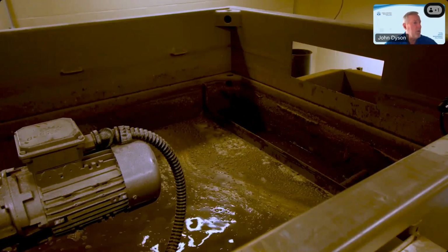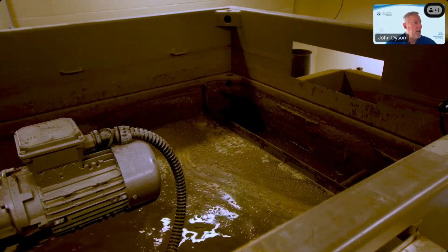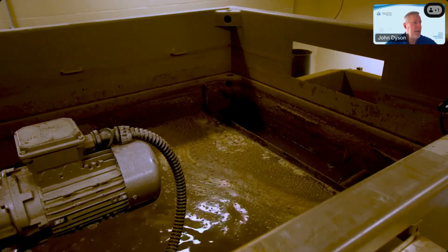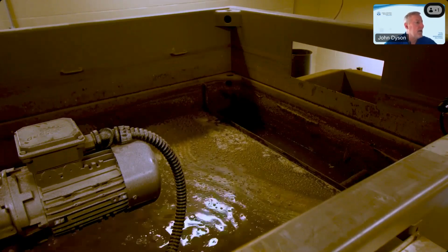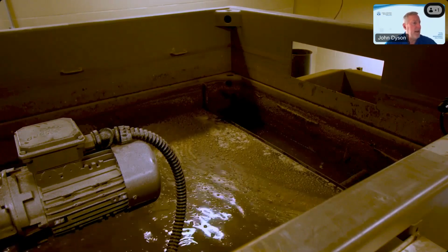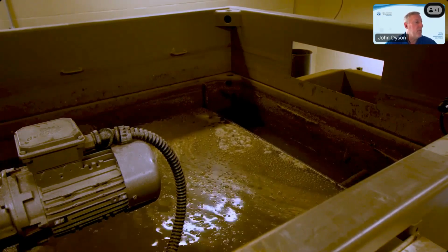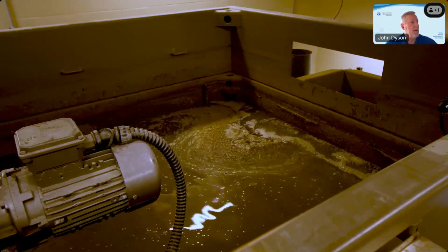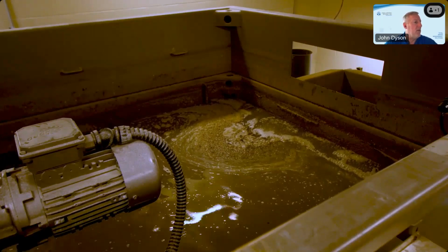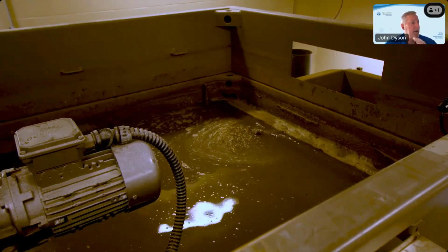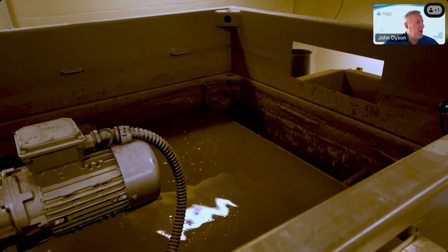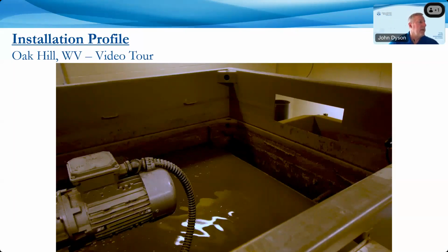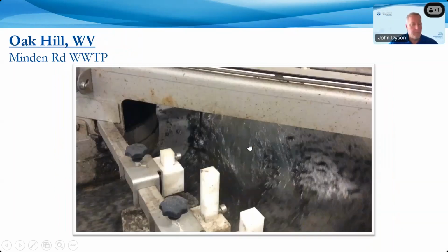Now scum removal, and I like to show this, is it's coming up like for a normal backwash, and this scum removal is generally done every 8 to 12 hours on a system. So basically, as it's coming up, again, the trough will become submerged here, but after it's submerged, the level comes up, and we open the valve on this trough, and because of that influent flow coming over the weir, we're able to clearly remove the scum that's there.